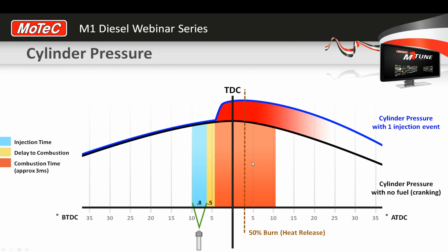So we're aiming to get that heat release location around 10 degrees after top dead center.